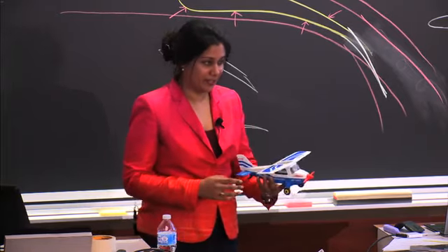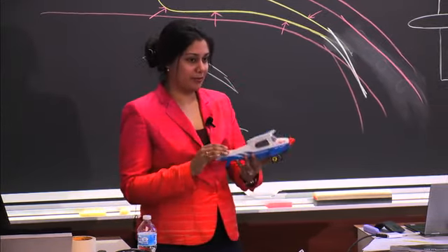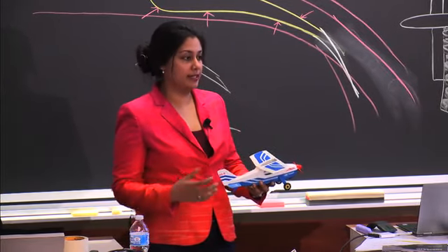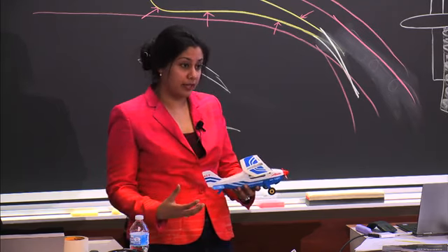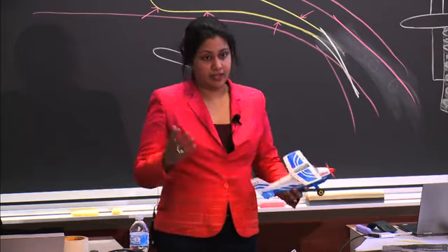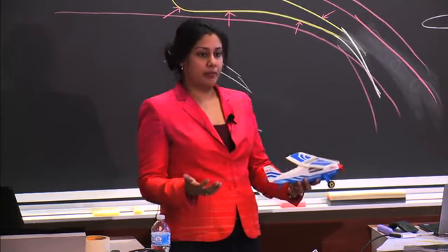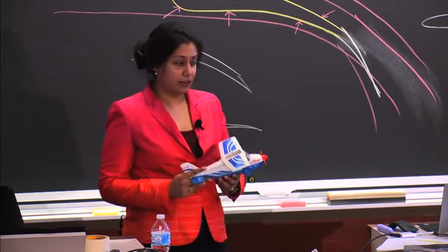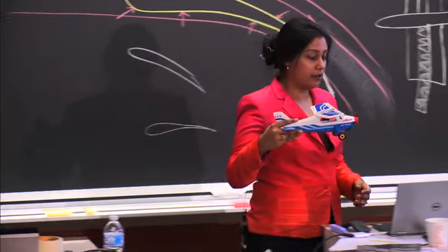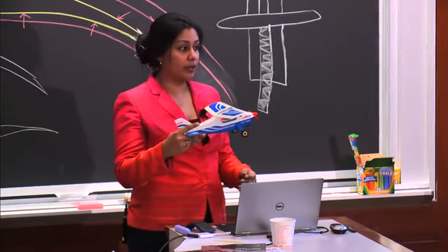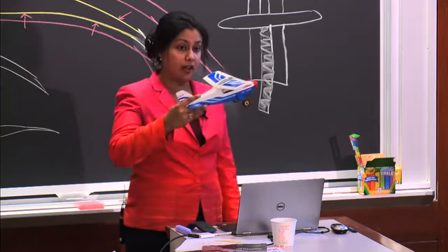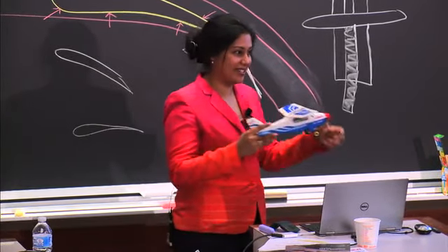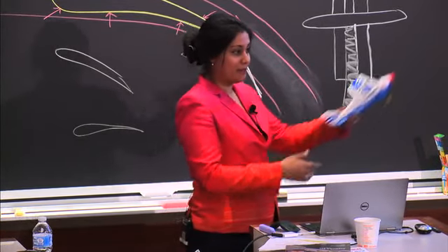this is probably the first part of your flight. After you did your pre-flight and your engine run-up, you pulled out onto the runway, and you'll have determined in advance the airspeed at which you should rotate. Now that's really important. With a Cessna 172, for example, it's around 55 knots. You want to look at your airspeed indicator, because if you just go by feel, you might notice that at much lower, like 40 knots, the plane has already taken off. You're already floating. You're flying, and you might be very excited about that, and you might want to just pull back on your yoke to take off.